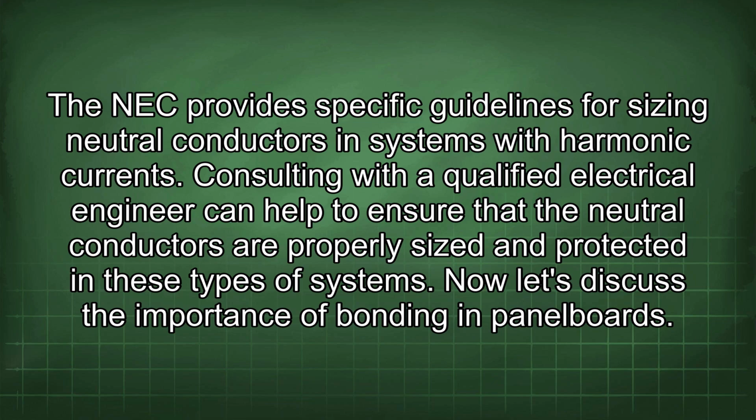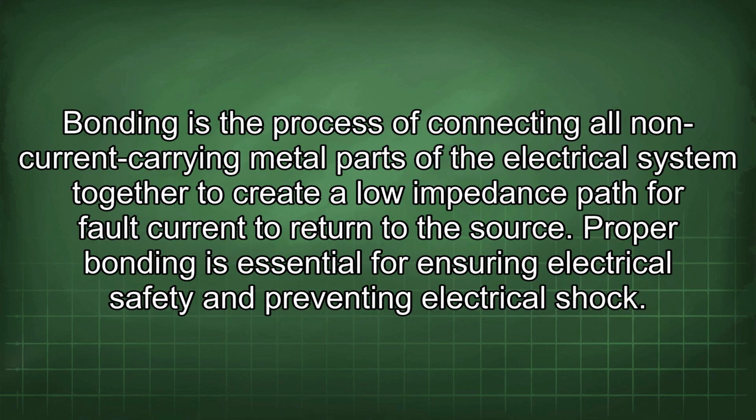Now let's discuss the importance of bonding in panel boards. Bonding is the process of connecting all non-current carrying metal parts of the electrical system together to create a low impedance path for fault current to return to the source. Proper bonding is essential for ensuring electrical safety and preventing electrical shock.